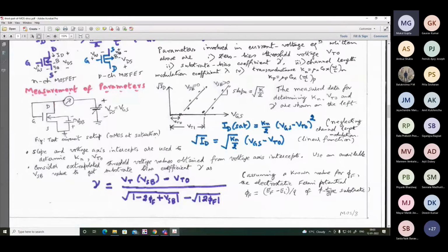The reason is that in a field effect transistor, in order to make the field effect prominent, you need certain PN junctions to be reverse biased, like the PN plus junction between source and body, and between drain and body. For all practical purposes, they should be kept reverse biased so that the field effect becomes prominent and not the BJT type of operation.